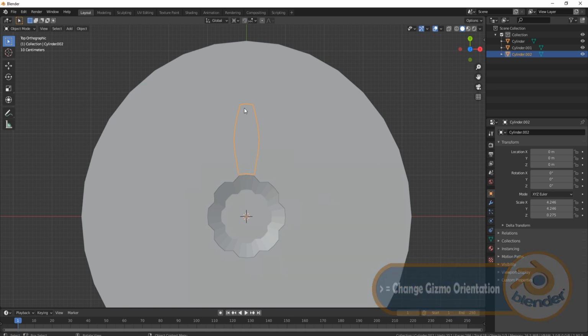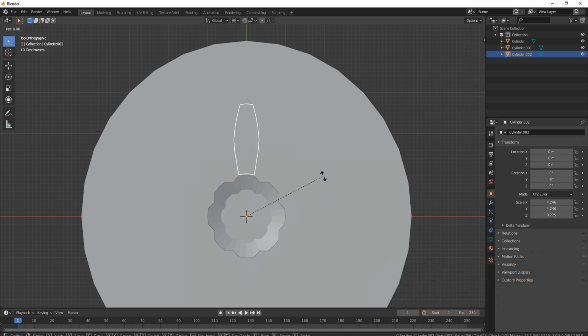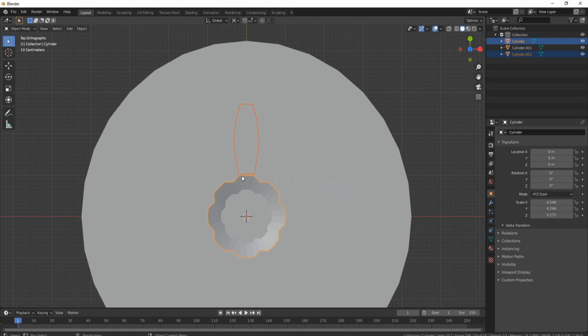And then what that does is, if I've got this grab now and I press RZ, it means it rotates around the center point of here, and that's what I'm looking for. So now if I grab both of these and I rotate them by 45 degrees, it will come to this point here, and I don't want that. So it needs to be 22.5 degrees. So if I press RZ and then on the number pad, 22.5, enter, you will see now that I can come into this one and do exactly the same thing as what I've got with this one.